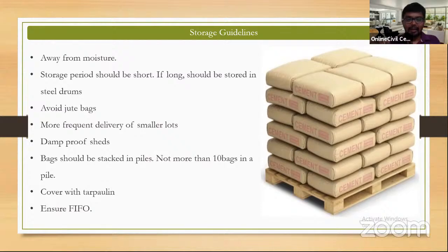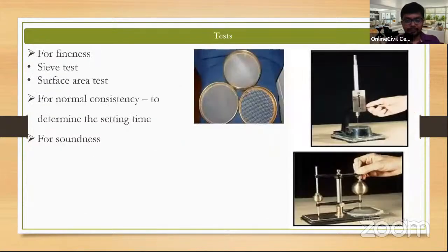Okay. And if you make some sheds, it will also be good. And after the sheds, cover that with plastic tarpaulin. That will be better. And if you are piling the bags, not more than 10 bags should be piled one over another, otherwise you can have unfavorable results.